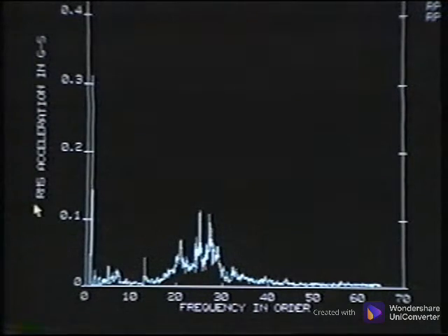With the same spectrum and acceleration, we can also see why we would not necessarily want to collect the data in acceleration and miss the significant contributions due to the lower frequencies. We need the best of both worlds. Let's look at the time waveform in velocity and acceleration to determine its help in detecting high-frequency occurrences.